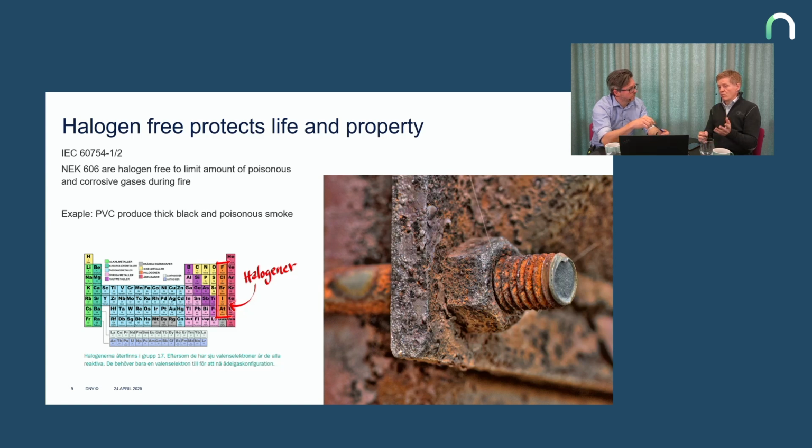And after a fire with halogen cables, let's say PVC cables, they were, by the way, prohibited by the 60092-360 standard back in 2014. But still, the outer sheath can be PVC. It's still allowed with ST1, ST2 outer sheath.